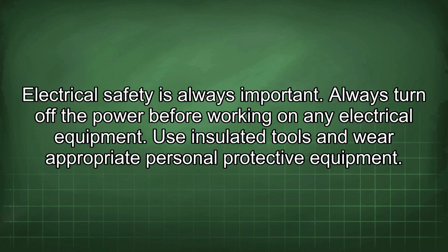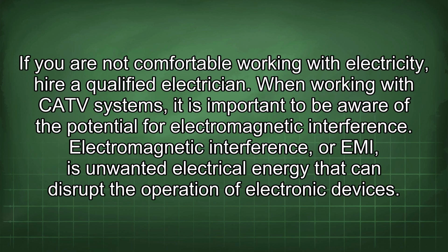Electrical safety is always important. Always turn off the power before working on any electrical equipment. Use insulated tools and wear appropriate personal protective equipment. If you are not comfortable working with electricity, hire a qualified electrician.